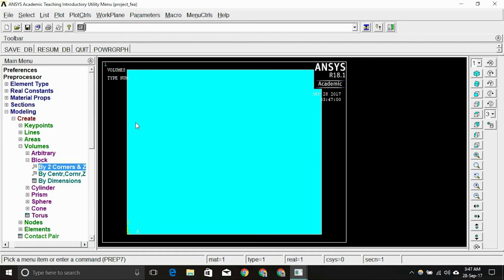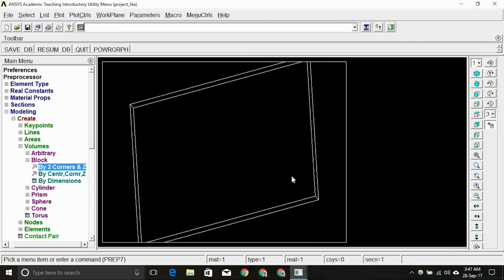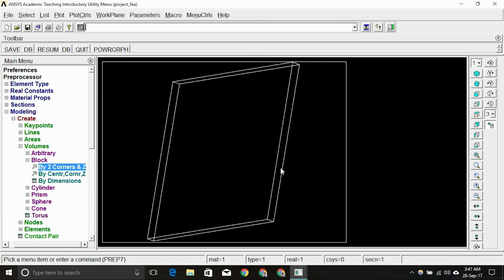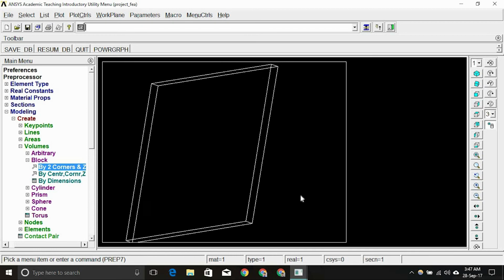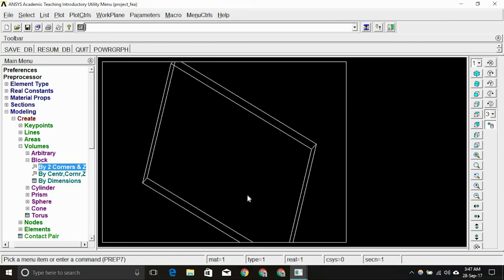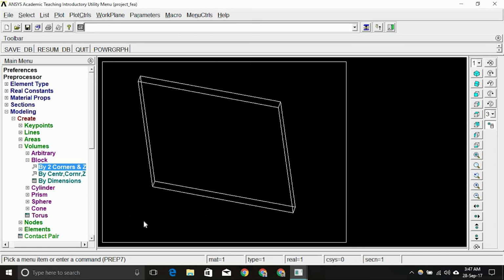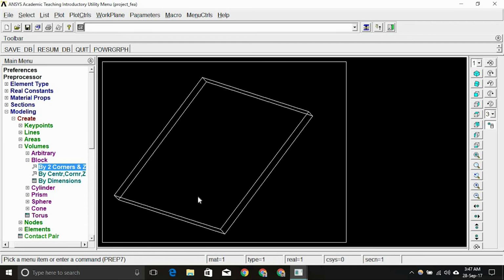Another tool we are discussing is the viewing tool. Go to the right side plane, go under dynamic model mode, and click on that. Now the mouse will turn into a different cursor. If you right click and use it, it will help to turn the model around. If you left click, it will just move around but it won't rotate the model. And the center click helps in zooming in and zooming out on the model. It also helps in rotating around a specific plane.